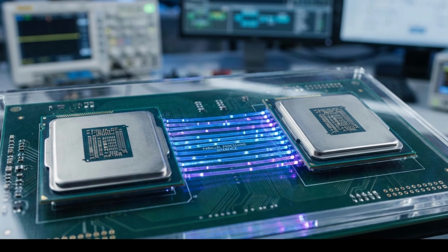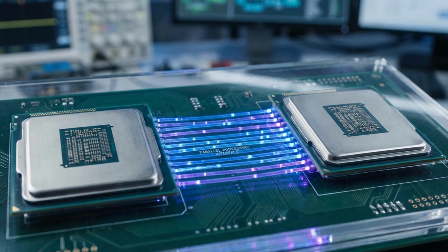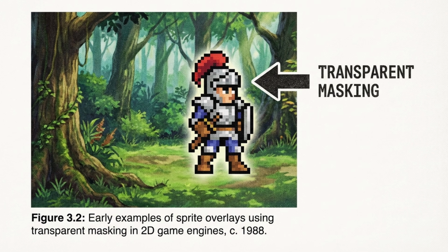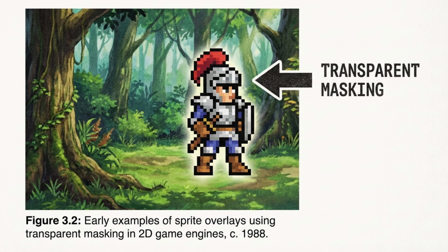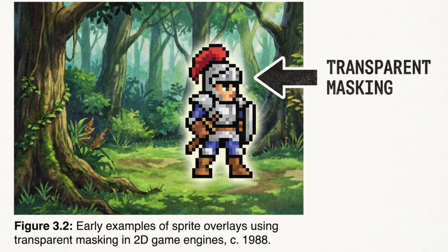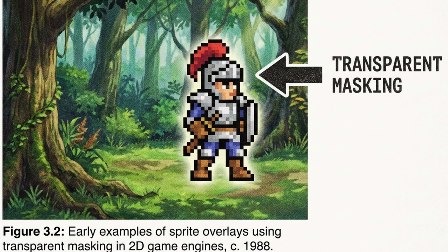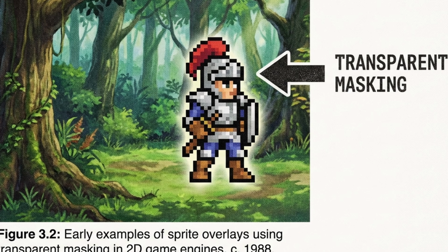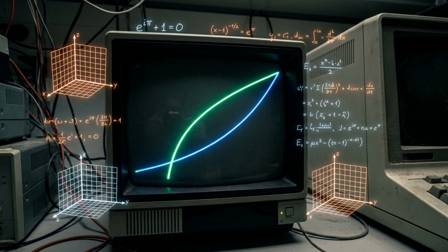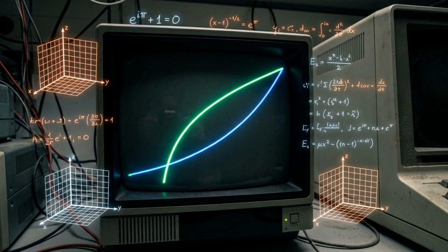The Amiga's blitter, however, executed these memory manipulations in parallel with the main processor. It was capable of handling complex operations natively in hardware, such as processing data that was not byte-aligned, and managing transparent pixels through cookie-cut masking, ensuring that a moving character did not overwrite the background scenery with an ugly solid box. The blitter even featured a hardware-accelerated mode for drawing geometric lines using the Bresenham algorithm.